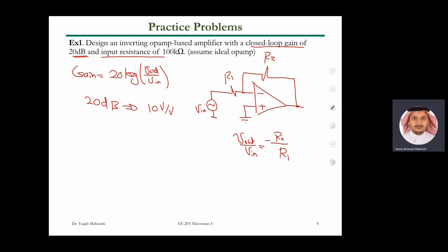If this is almost ground, you can see only R1. Imagine, Shabab, this is virtual ground. Can I say this? This is virtual ground, because V positive equals V negative. And then you can see only this input impedance or input resistance. So, if it is confusing, we just take this one as R1. If R1 equals 100K, how much should R2 be to give you that much gain?